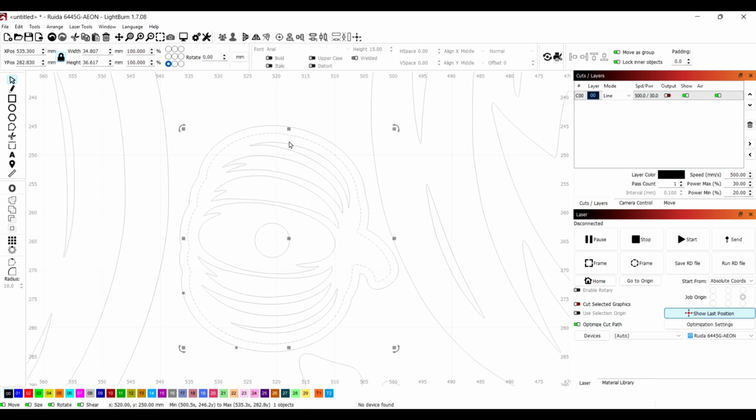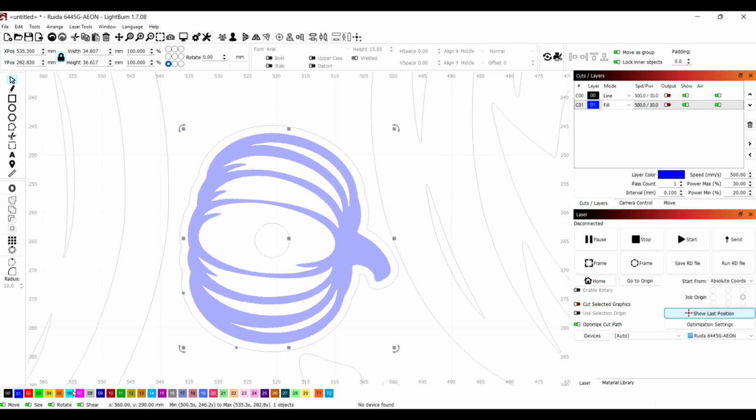So we need to individually select those parts, or again drawing a bounding box around them just by clicking and dragging, and then holding shift key as well is important because that keeps everything going. And then you can see just how I'm doing it, just drawing a wee box over them. It's easier than trying to find the exact point to select sometimes. And then we can group them again and then change that setting. We need to change the colour and then make sure it's a fill, so you can see I've done that there.